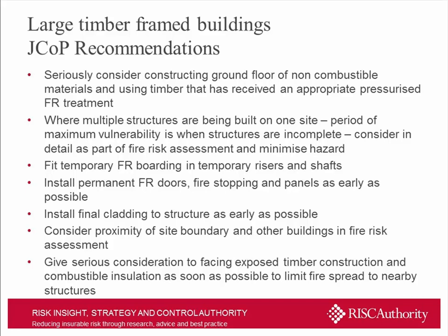It also reflects on the specific risks that exist in that sort of environment where you've got multiple structures built on one site, the potential for fire to spread during that construction phase when there's no installation of anything that's likely to limit the potential for ignition or limit the potential for fire to spread from one space to another. It then goes on to make recommendations for ensuring that where possible the structures are effectively separated, that suitable compartmentation is installed, and that fire risk is minimised by reducing the potential for ignition through managing ignition sources effectively.